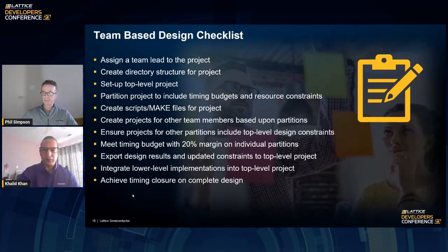And if there's any timing closure or functional challenges, these engineers will work together with the team lead or system integrator to resolve these. Now, when it comes to secure or safety critical designs, there may be other aspects to completing the designs, such as you may want to use specific features such as TMR, triple modular redundancy, on key blocks. And I'm now going to hand you over to Khaled, who will discuss some of the techniques that can be critical to these particular use cases.